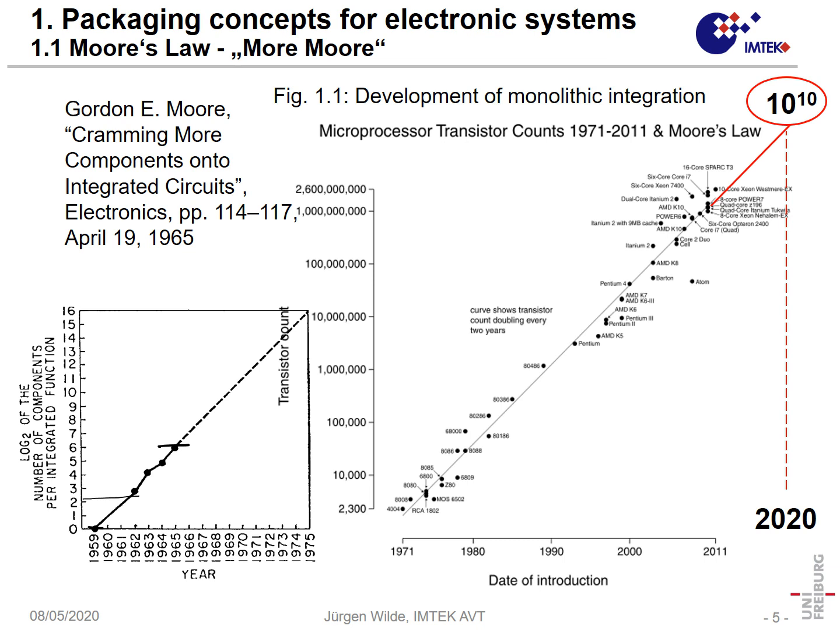Okay, from 10 to the power of 2 to 10 to the power of 10, so it is an increase by a factor of 100 million. And of course, that could only be achieved by, first of all, making transistors significantly smaller, going down from many micrometer size to maybe 10 nanometer size. On the other hand, it was also important to make larger and larger wafers.